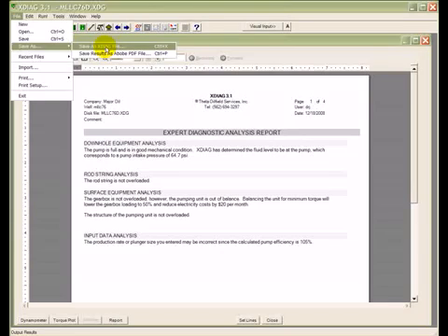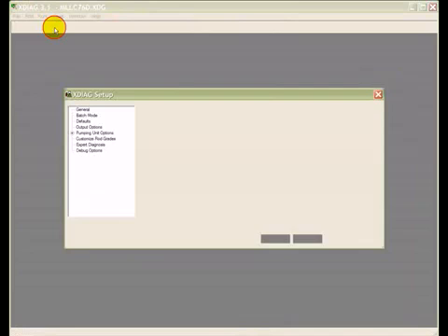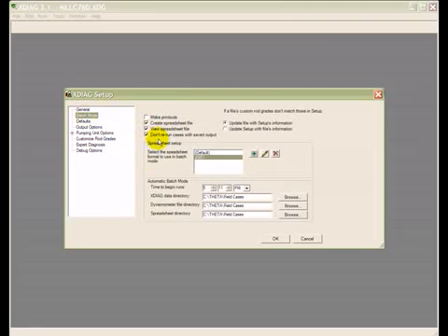way you can then import into your Rodstar program. Another useful section of the program is the setup, which allows you to change your system of units. You can specify the spreadsheet that you want the program to create when you run in batch. Running in batch allows you to have the program run a whole bunch of cases for you automatically by simply selecting more than one file when you select open file.